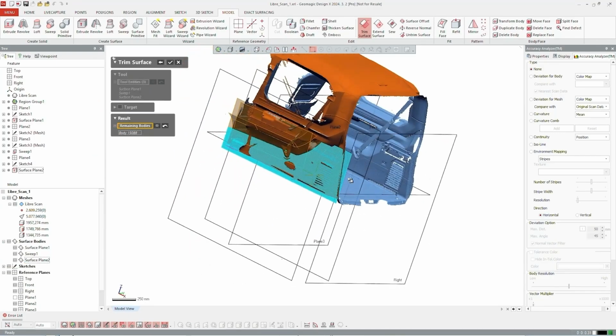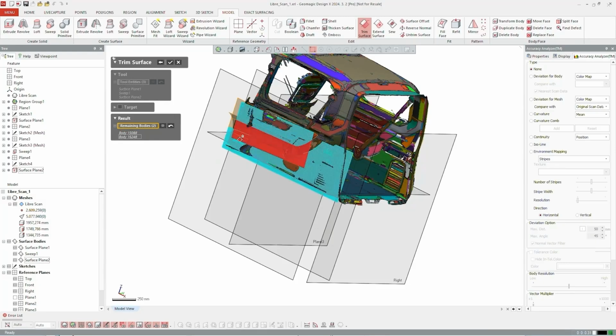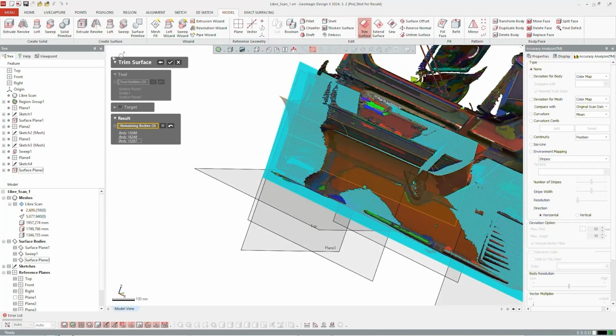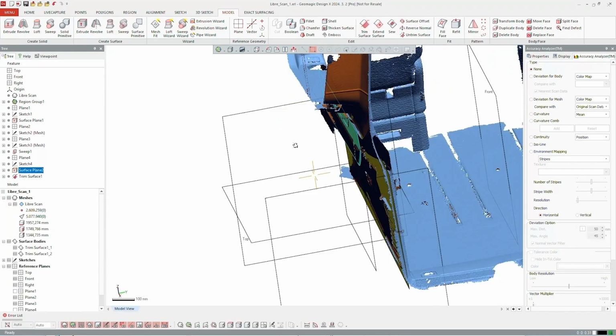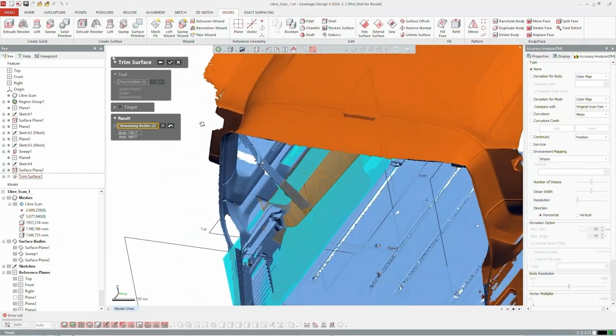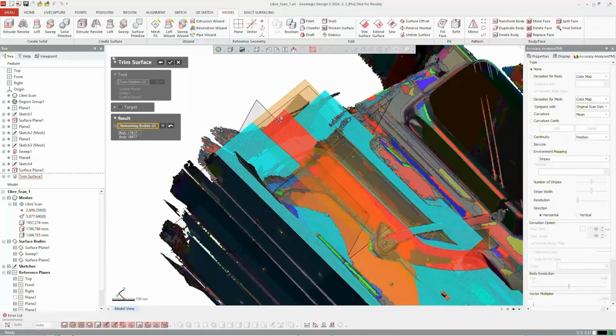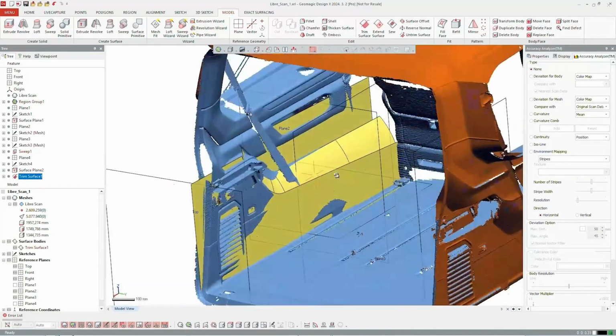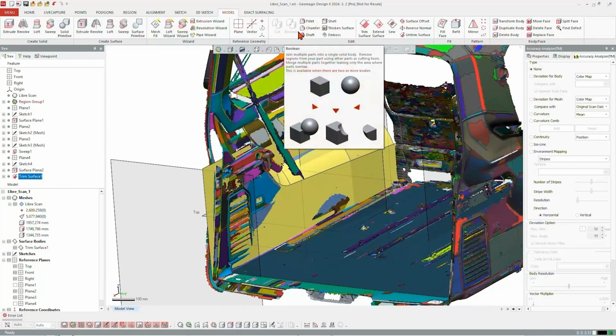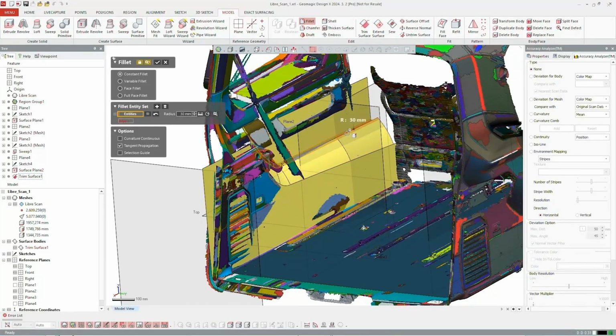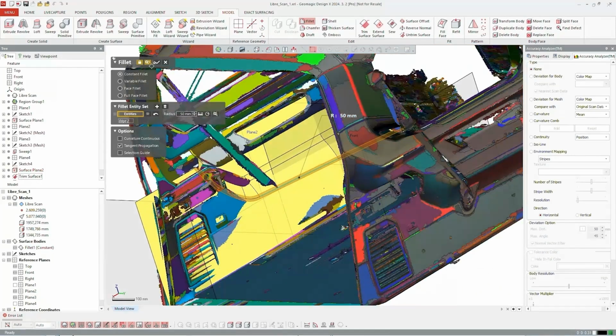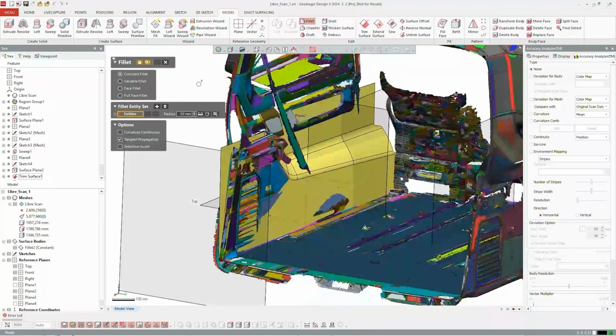And then these surfaces can be trimmed. The result will be a single surface body. If you select too much, you can always re-edit to optimize the wanted outcome. Next would be to add fillets to get a nice smooth connection in between the surfaces, and to adjust the design of our wanted result later on.